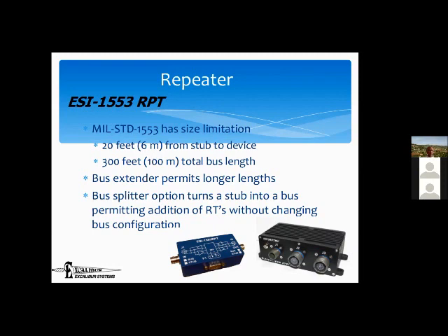In addition, 1553 is not only used on aircraft. We've seen more and more uses of 1553 on naval ships. And ships are very large. They can be multiple stories tall, as well as very large from, I think it's bow to aft, but I don't really know. So for various reasons, 300 feet may not be enough. Okay, but you need 500 feet. And yet the spec says don't do that. So now the question is, why does the spec say not to do that?